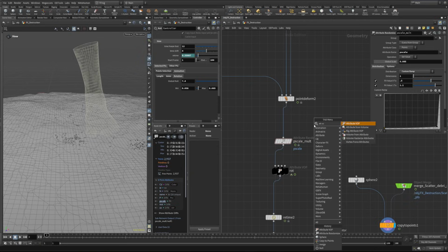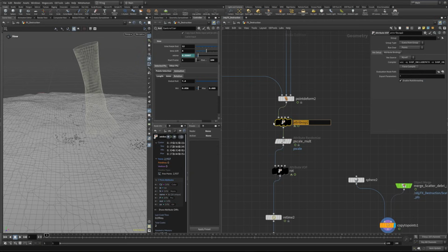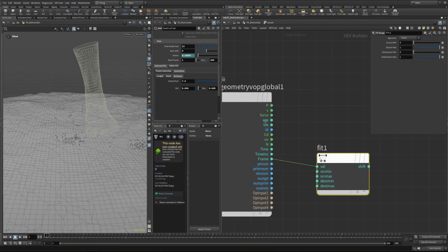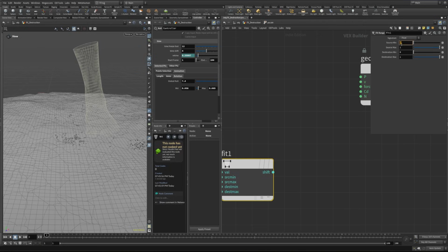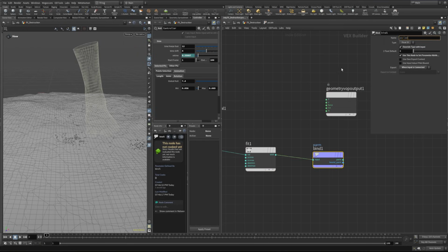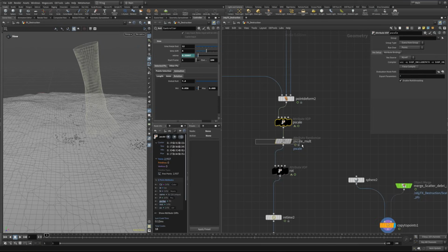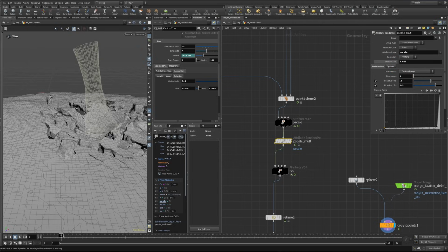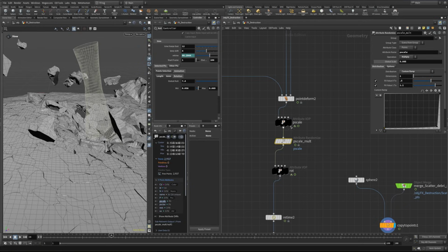And we're using an attribute warp over here, place it in here, calling it p-scale, diving in. And we're starting with our frame again, plugging it into a fit range, using a value from 1 to 15. And this goes into our bind export. And this will be my p-scale. With this, over the first 15 frames, from 0 to 1. And if we go into the p-scale multiply, we can go to set value and use a multiply. Now, after frame 6, still not applying because why they are not visible here.